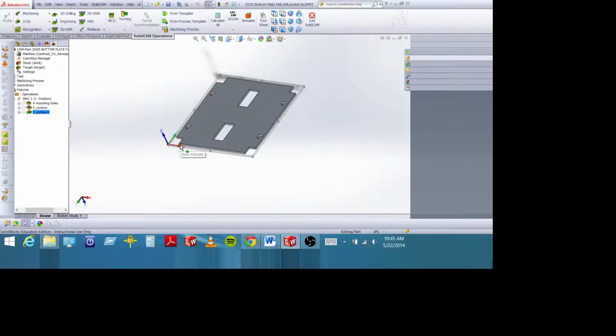you know you're cool and you can stop. You can pull this material out, undo the clamps here, and then you can just snap that part out, kind of like little models that you did when you were a kid. Or you can X-Acto knife that really thin sheet of aluminum down at the bottom, and then fatigue that aluminum by bending it back and forth and then filing that edge. Remember, aluminum foil is like 3 or 4 thousandths thick, so you leave 20 and start stepping down, and when you get close to that 3 or 4 thousandths, it's just going to be like foil and you can just peel it off.